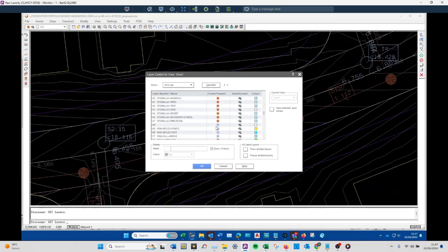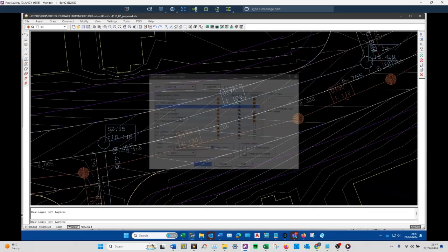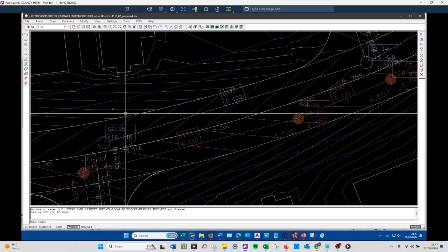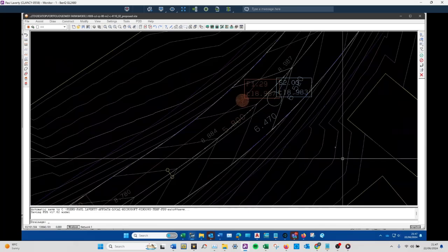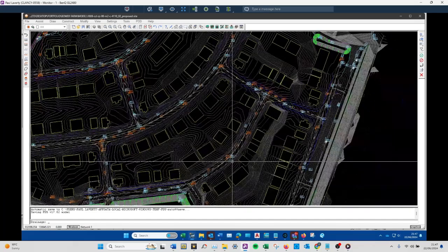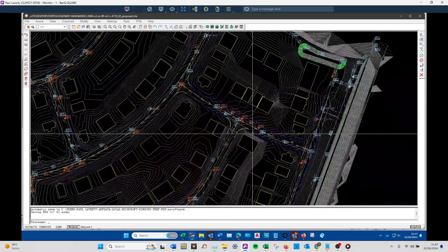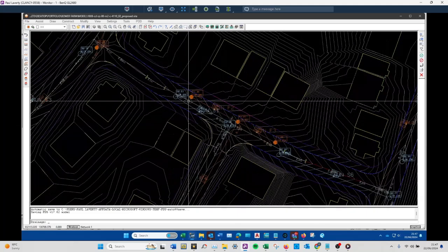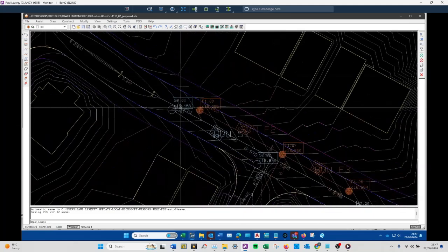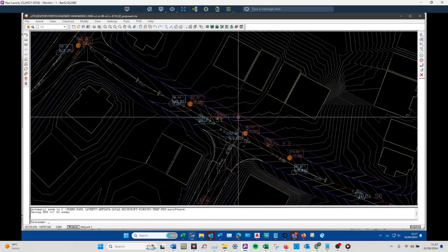So we put everything into this folder so that when you jump back and forth, you're not having to go from the PDS model back out to the calculations folder to get to the drainage model, then going back into the drawings folder to go into the PDS to edit the ground model, and then you're not spitting something out into the CAD drawing, and then you're going into the CAD drawings folder. It's more localized. You have fewer folders to go back up the chain, if you will. So the flows model is just right there because you're going to be doing changes to both of them at the same time as you go through it.